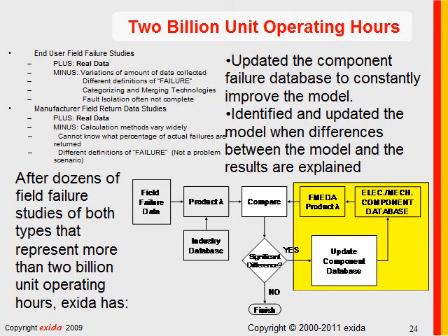And it turned out that they were leaking current in the reverse direction. Now, those diodes were on there for purposes of overvoltage protection. And they would conduct when the voltage exceeded the breakdown voltage of the diode. And after a brief period of time in the field, apparently the diodes would start leaking current.